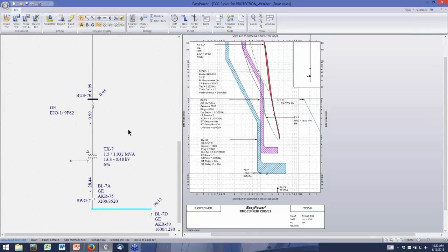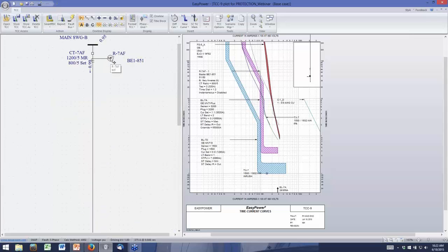All right, so there's one other complication, and that is we have to look at symmetrical versus asymmetrical current. In general, what we are displaying here is going to be RMS symmetrical current. But some overcurrent devices are sensitive to the asymmetrical current, some of the instantaneous trip elements. The newer relays like this one will have what they call a DC offset filter, which means it will not respond to the asymmetrical portion of the current. But you have to look at that on a case-by-case basis.